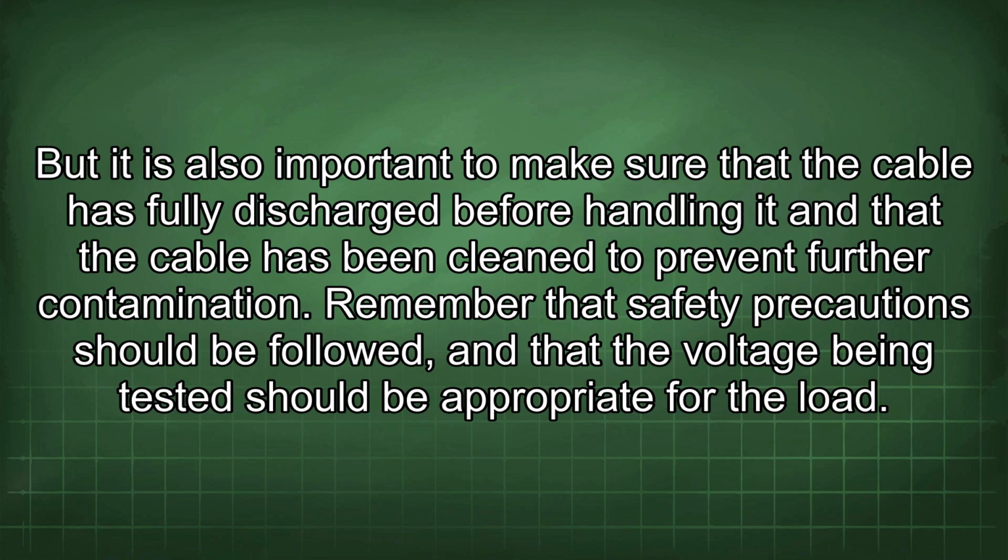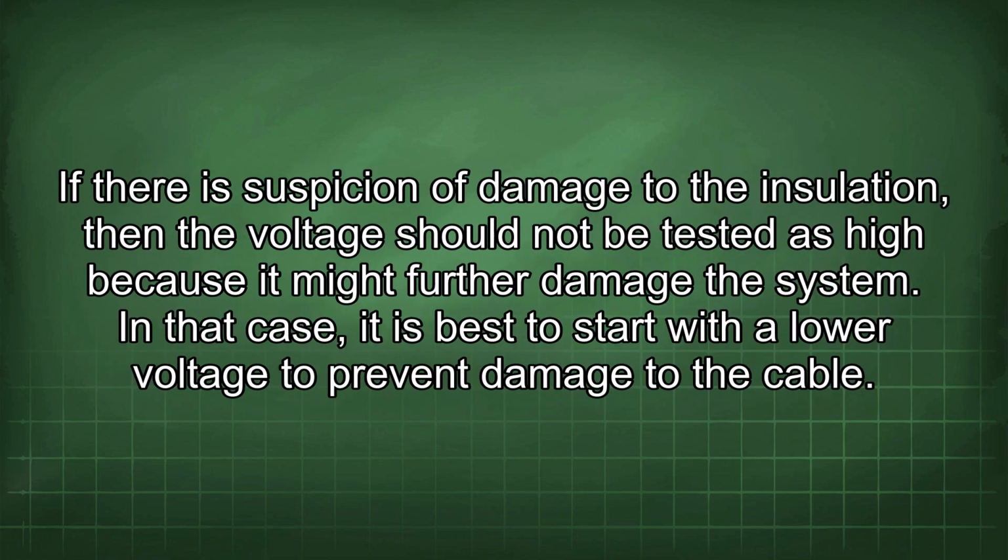Remember that safety precautions should be followed and that the voltage being tested should be appropriate for the load. If there is suspicion of damage to the insulation, then the voltage should not be tested as high because it might further damage the system. In that case, it is best to start with a lower voltage to prevent damage to the cable.